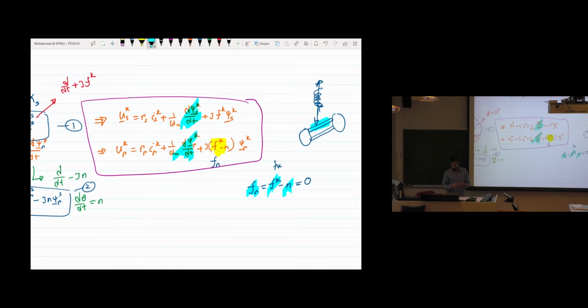This means there will be no current induced, because no voltage will be induced, because there is no rate of change of flux. Therefore, we get 0 torque. That's the important thing: to get torque, there must be a difference between the frequency of the stator flux and the speed of the machine.